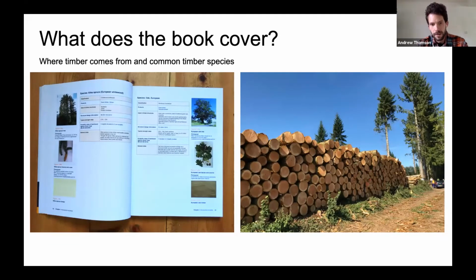And I think those things also touch upon some of the sustainability issues that James mentioned, in terms of, timber's not a renewable resource, but if you're in the southeast of England, you might be able to get glulam sweet chestnut from coppice woodland, and that is renewable. That's cyclic, that's part of the maintenance of those stands.